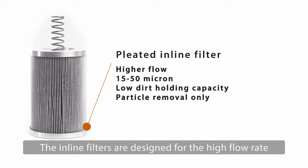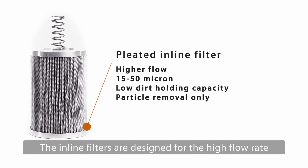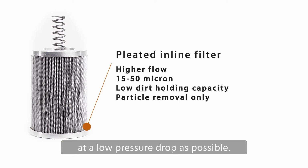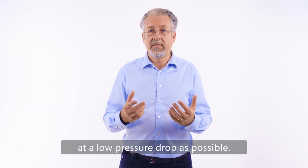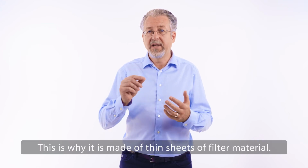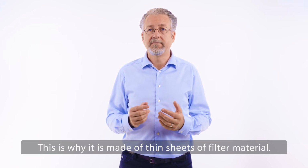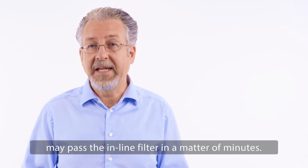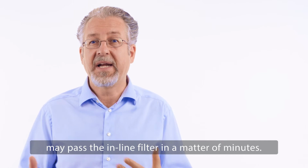The inline filters are designed for the high flow rate and high pressure coming over the filter at a low pressure drop as possible. This is why it's made of thin sheets of filter material. The whole volume of the oil system may pass the inline oil filter in just a matter of few minutes.